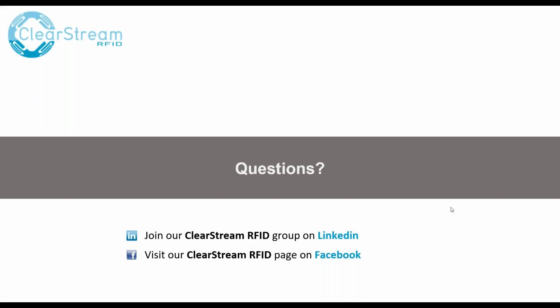So reader modes put the reader into different modes, so to speak, so it knows which use case it is in, what it needs to perform in terms of performance, and what it is trying to read. Read all the tags that possibly I can, or read certain tags at a certain distance, like in the demo we saw, where you could change the power of the antennas. That's one example. But even at the reader level, there are certain configurations. Under the reader mode setting, the two main specifications it uses are the sessions and the search modes.